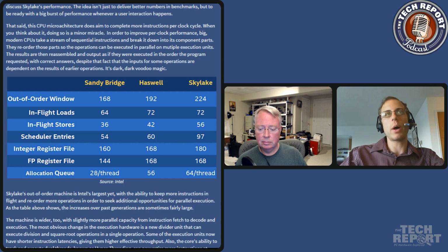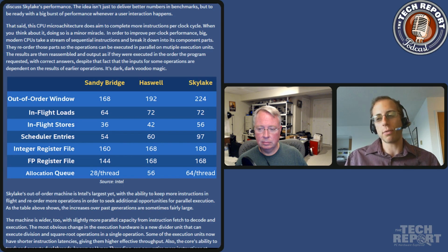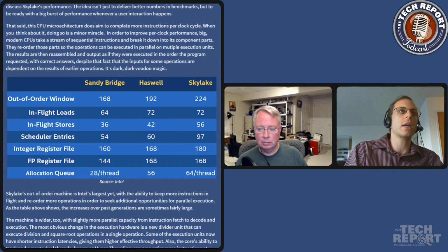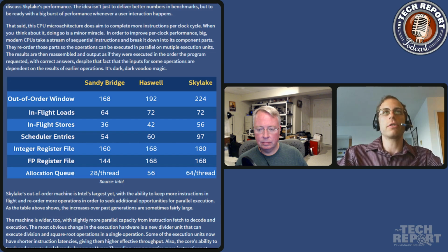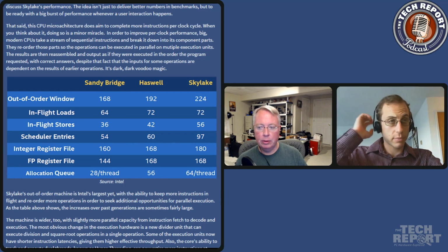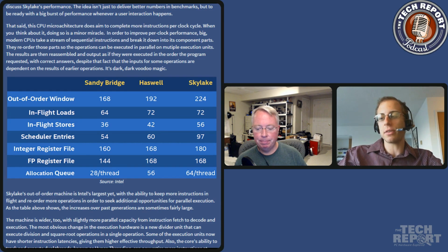Like, you could say, if we have 2 threads, one gets half of the scheduler and the other gets the other half. Well, what if one of those threads stalls? Then maybe we should clock gate off half the scheduler. I don't know how they implement it, but there's a ton of tricks you could play like that. And obviously they're pulling out the tricks. This is a late-stage architecture that has a lot of complexity and yet manages to be more efficient than prior ones. Yeah, exactly. And I think that's the bottom line: as these structures get bigger, they also have to get more efficient.